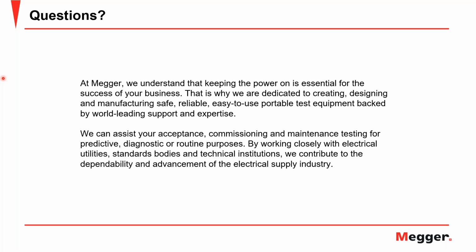A 32 element is a reverse power element. That means that in order to have power, you need both current and a voltage. You must have a voltage. The whole presentation that Abel had, he was talking about a polarizing signal and an operating signal. The operating signal is always a current, but the polarizing signal could be a voltage or it could be a current. Therefore, you don't have power if you only have currents.